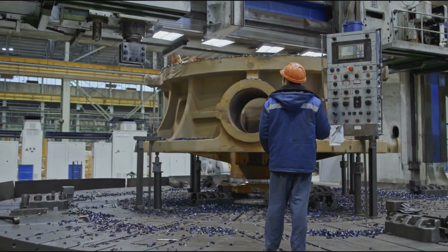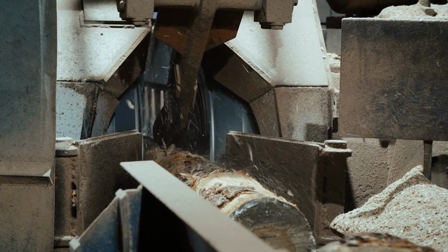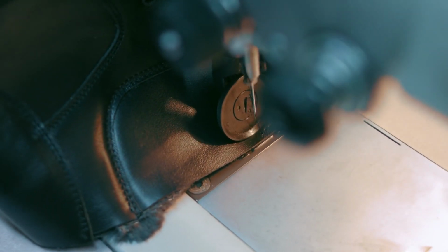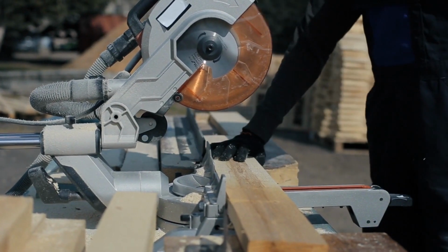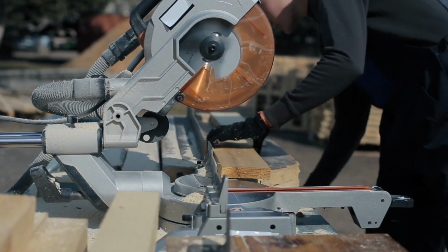Okay, so unlike Class 1 and 2, Class 3 areas don't have airborne materials that can catch fire. Instead, the risk comes from flammable materials that build up on floors, counters, and equipment. Sawmills, leather plants, and shoe manufacturing are all examples of Class 3 locations. Machinery in Class 3 areas should be well insulated and always kept and run within safe temperature ranges.